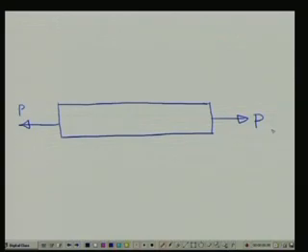So, you understand the material is subjected to what we call tension. Once we put the material in tension, if you have seen this type of material testing, you must have noticed that if it is a ductile material, it undergoes some reduction in cross sectional area in this particular zone.